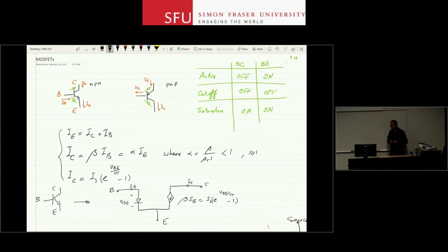And in analog circuits, like the diode circuits that we analyzed in the past, you have to assume an operating region for the diodes and then go and verify your assumption. Same thing here. You assume the transistor is in one of those operating regions, and then at the end of the story, once you do the calculations, you need to verify the assumption.